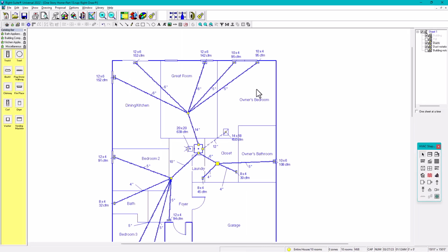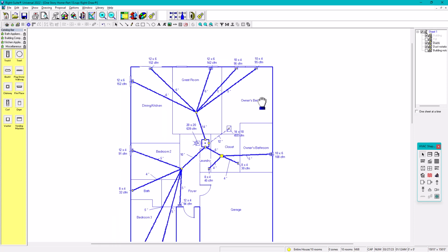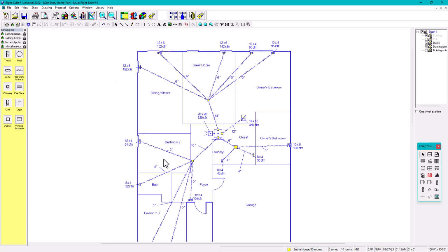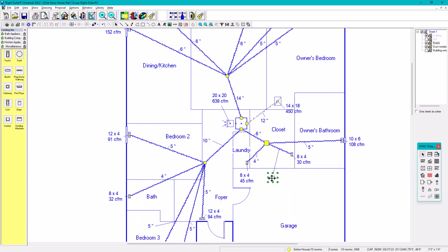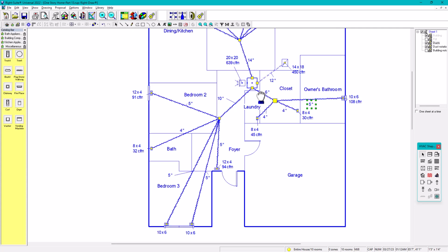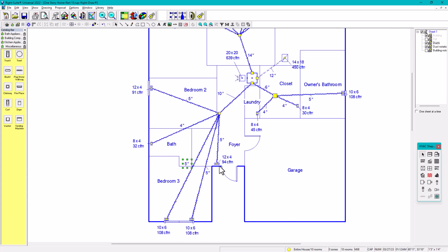Okay, now what else can we do in here to make this a little bit nicer or look better? So what we're going to do is put this a little bit closer here, and again, it depends on everyone's taste. Everyone is different, but usually I like doing it this way. All right. Now, what else can you put in here? I've shown in the other videos that we have this catalog bar. In the catalog bar, you're going to have images that will not affect the duct calculation or the heat loads. These are just annotations, okay?